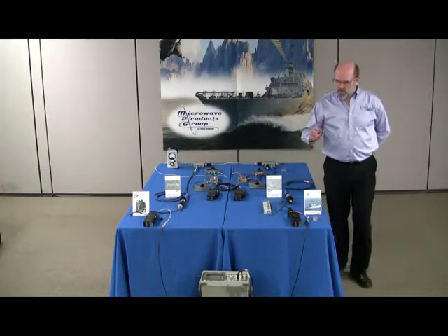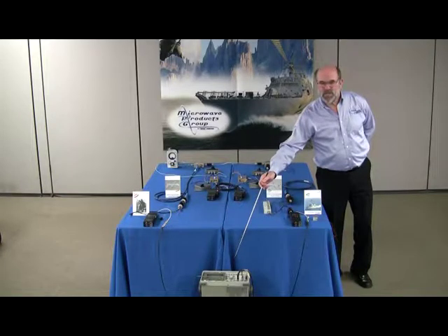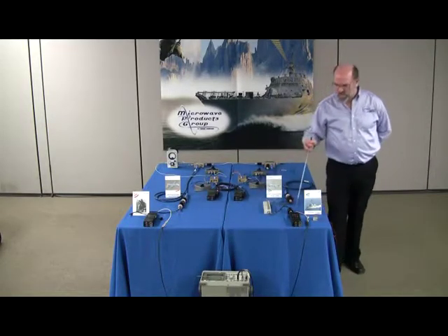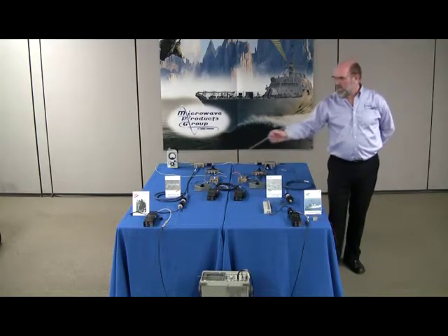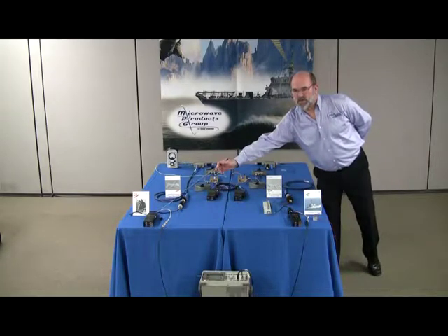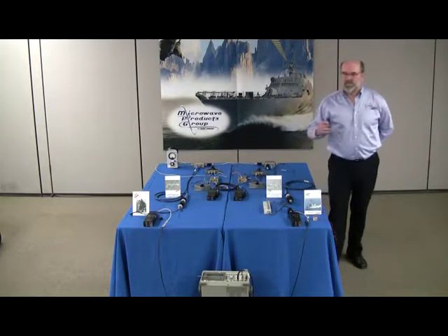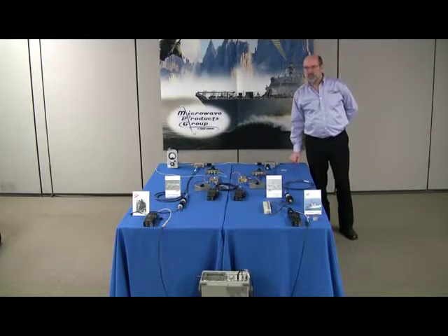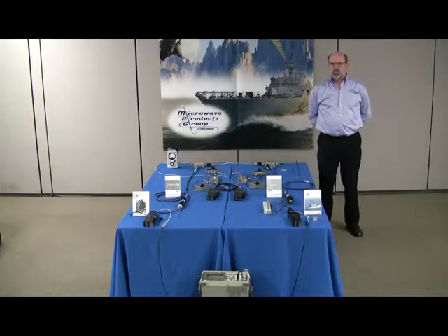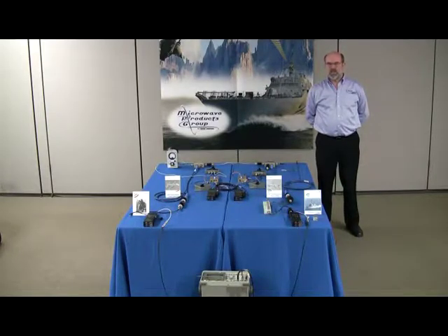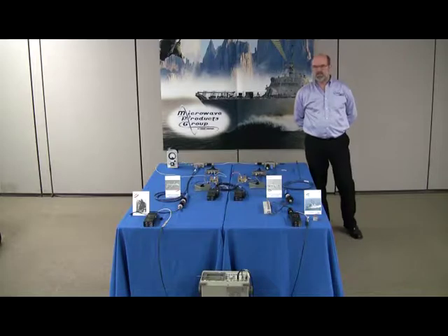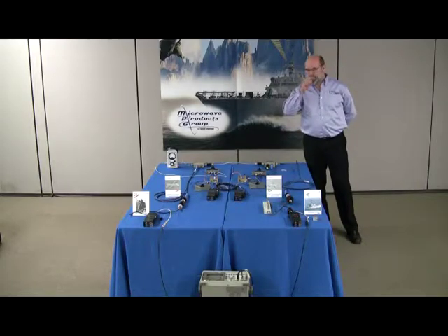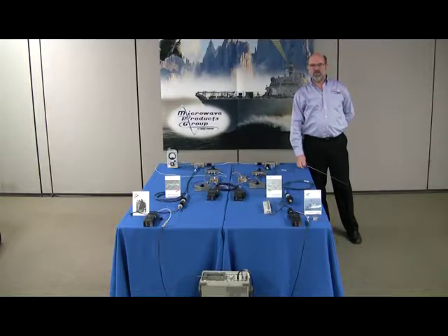An audio signal will be introduced by the communications system analyzer at the uplink transmitter and analyzed at the downlink receiver for its signal to noise and distortion, or SINAD, value. A value of 12 dB will be considered the minimum acceptable signal quality level as given on the communications system analyzer. We will conduct the demonstration while operating in the 30 to 88 MHz frequency band.